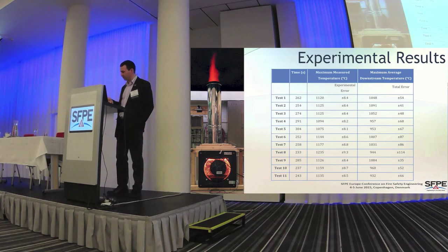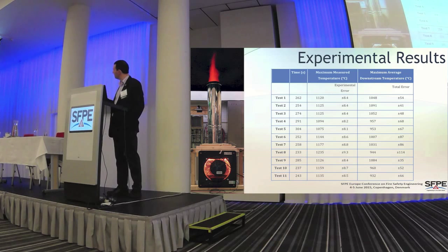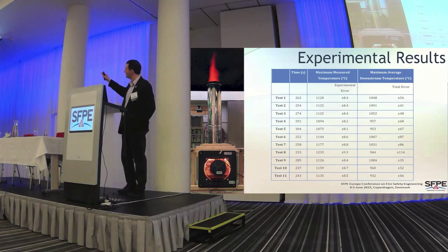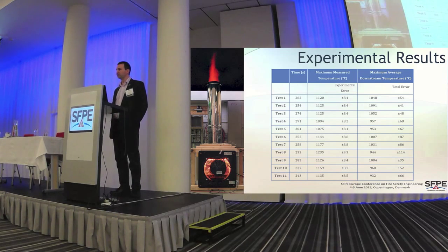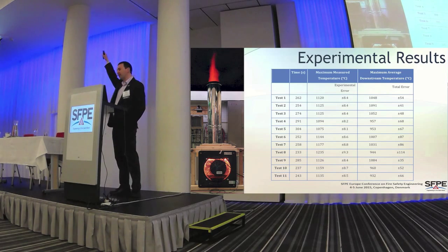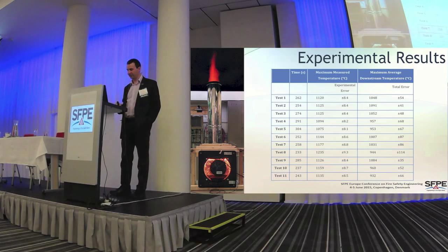By the way, I should say in the picture that I'm showing you at the side of the screen, the flames at the top of the duct do not mean that the flames have been the whole way along inside the apparatus. That's just demonstration of the fact that there are unburned flammable gases coming out, meeting fresh oxygen and burning at that point. There was actually no flame inside the chimney. It burned out somewhere inside the duct. Unburned gases went up the chimney, and then when they encountered fresh air at the top, that's when they reignited.